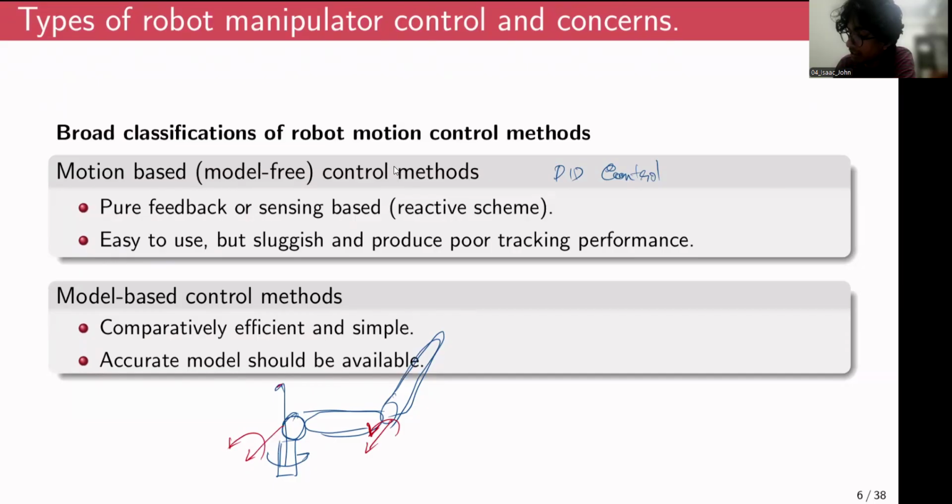When the robot is fully stretched, the rotational inertia about this vertical axis is going to be very high, right? If it is fully stretched, the moment of inertia would be proportional to the length of the fully extended part.